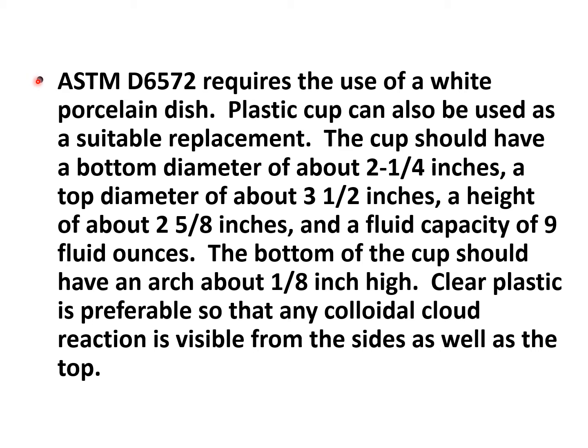ASTM D6572 requires the use of a white porcelain dish. A plastic cup can also be used as a suitable replacement. The cup should have a bottom diameter of about 2 and 1/4 inches, a top diameter of about 3 and 1/2 inches, a height of about 2 and 5/8 inches, and a fluid capacity of 9 fluid ounces.